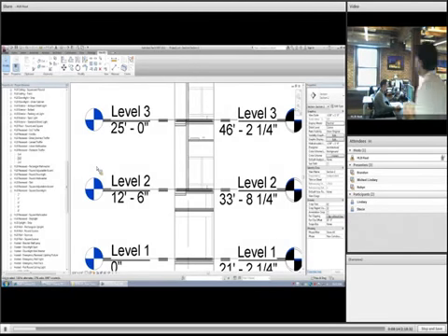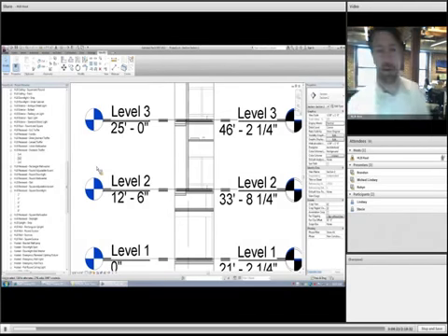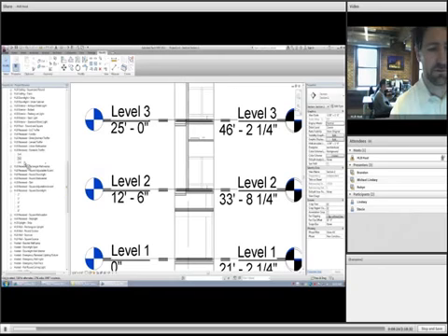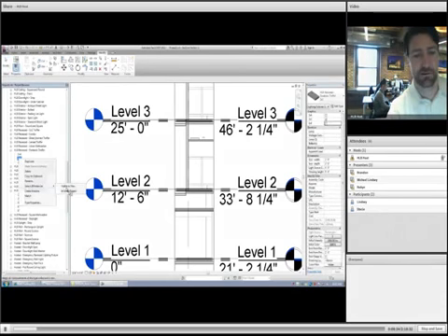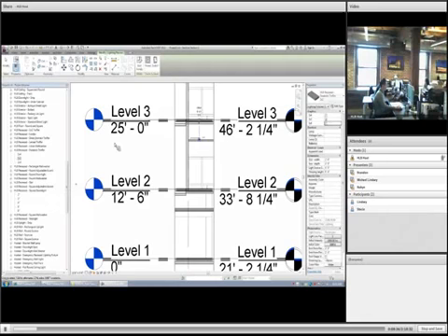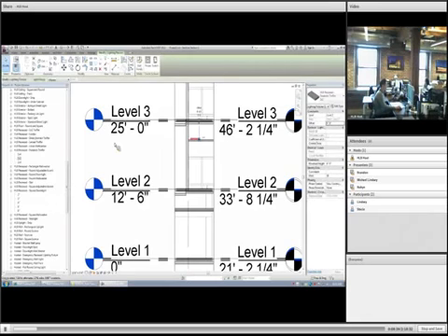Yep. So if it's not showing up, a few things you can do. If you're trying to seek out a fixture, you can go into your project browser and browse to that fixture. You can right-click on it and say, select all instances in entire project. And it goes and finds all of them in the project. Maybe that helps you then identify it.